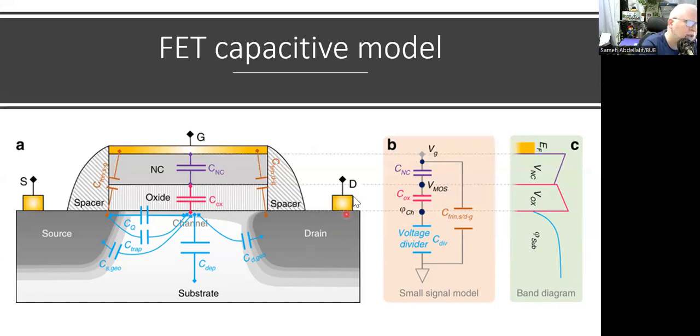For example, here, if you add a positive voltage to this N-type drain with a grounded substrate, that means that you force this p-n junction to be in reverse bias, which means that you increase the depletion region. So the existence of these capacitors may differ from one region of operation to another.